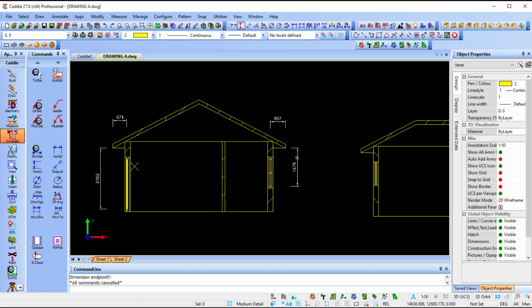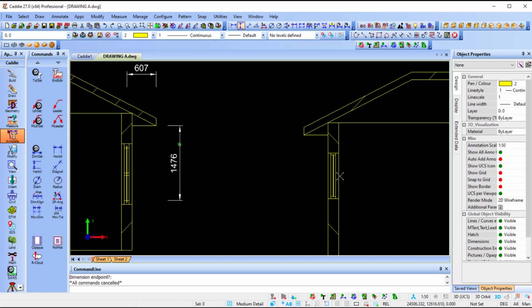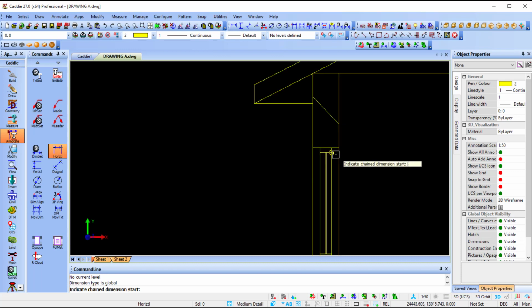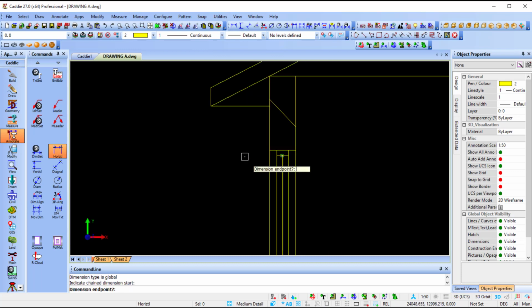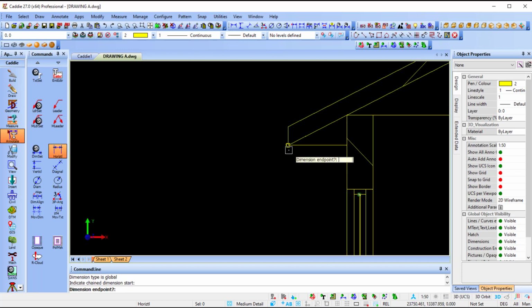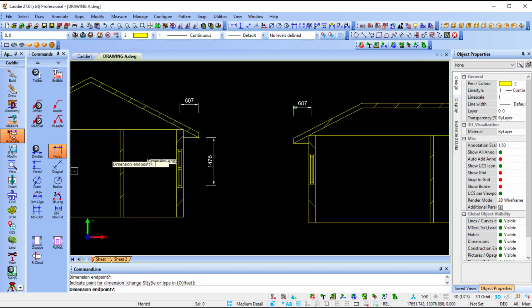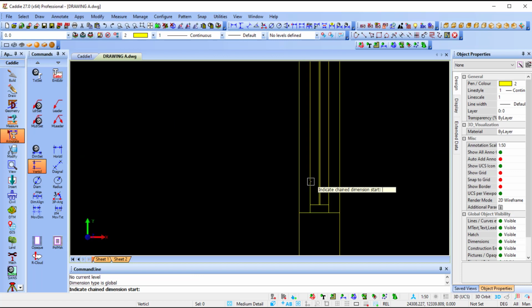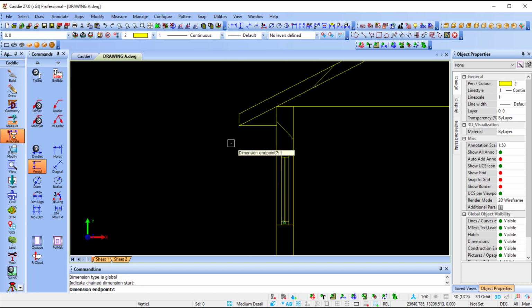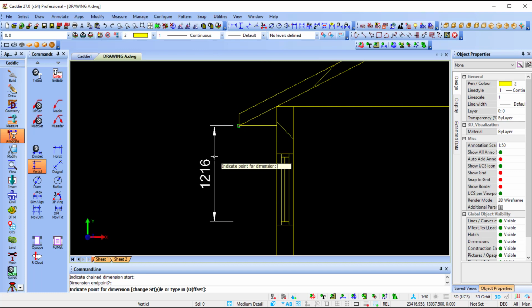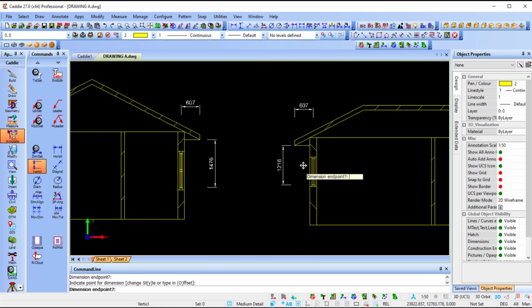So I've got my sliding door dimensioned, I've got my bathroom window dimensioned, so it's now only my room windows PT129 that I have to dimension. So my P value, outer face of glass to extent of shading, as well as my H value, base of glazing to shadow cast edge, and I can place the dimension.